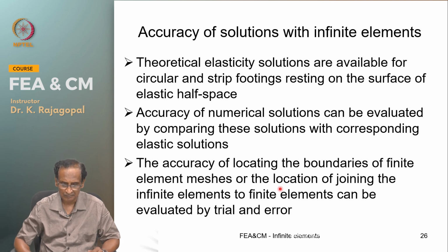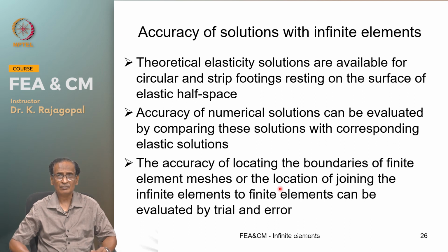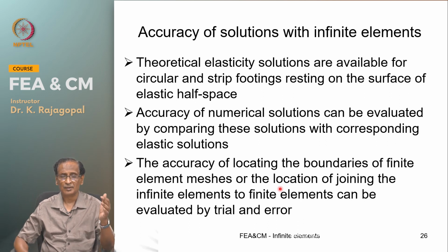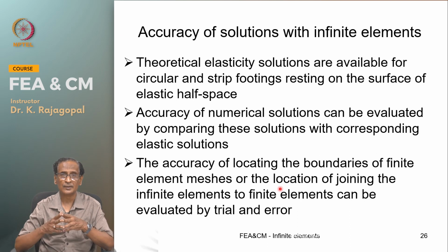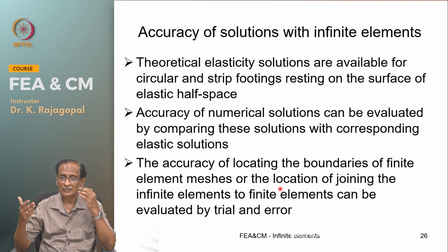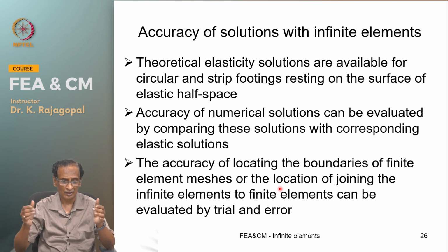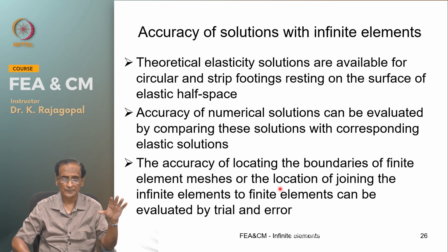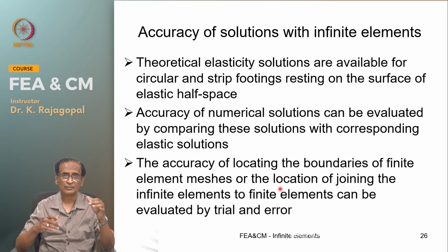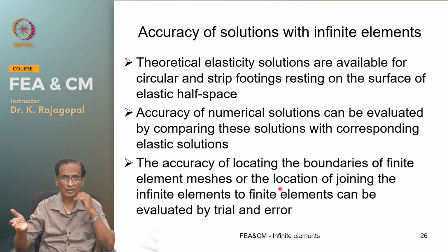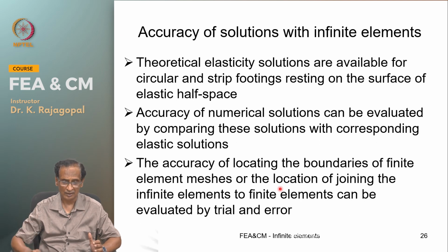So, the accuracy we can easily check, because we have a number of theory of elasticity solutions for the loading on the surface of an infinite soil domain. The circular loading on a circular footing, or a continuous strip loading on a wall footing, and so on. We can compare our numerical results with these theoretical solutions for verifying our accuracy.